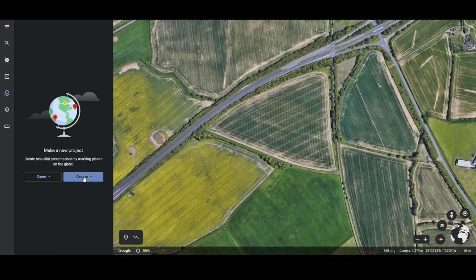This section looks at importing a KML file into the DJI Pilot app. Importing a KML file is a useful feature when you're working over a large site, as well as if you want to prepare a mapping mission back in the office or on your computer. Google Earth can be used to draw a KML file.